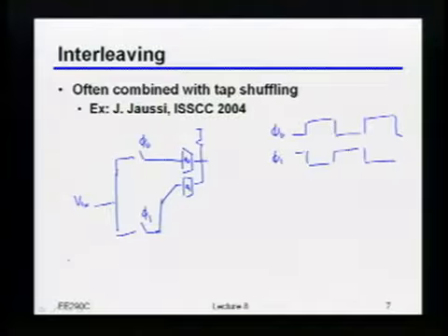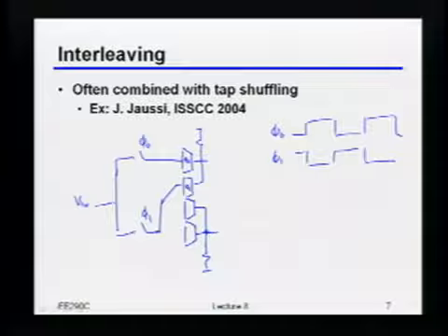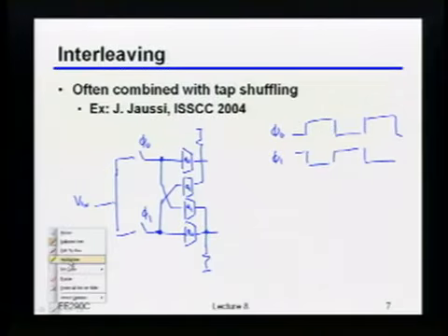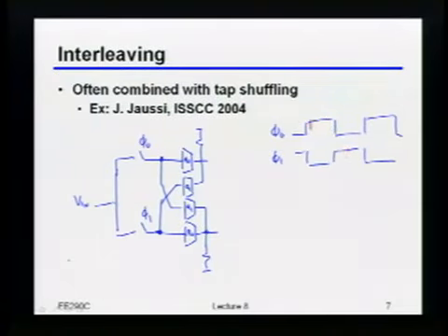Okay, so similarly, you can imagine you end up doing exactly the same thing on the other clock phase, just that the meaning of everything is reversed, right? So in other words, here, my A0 would be coming straight from that phi 1 sample, right? Because that's my cursor. And my post cursor would be coming from the other interleaved phase, right? Because very similarly, if I was at this time, then one before me was phi 0. Okay? Does this make sense to people?